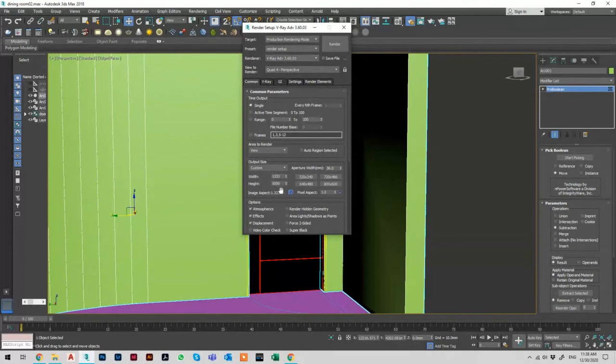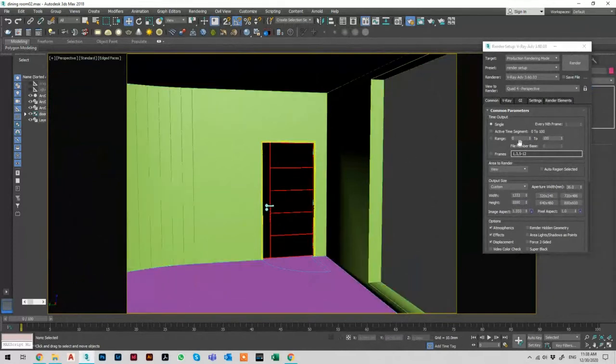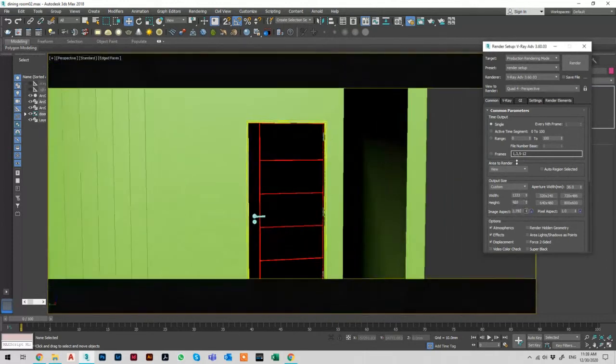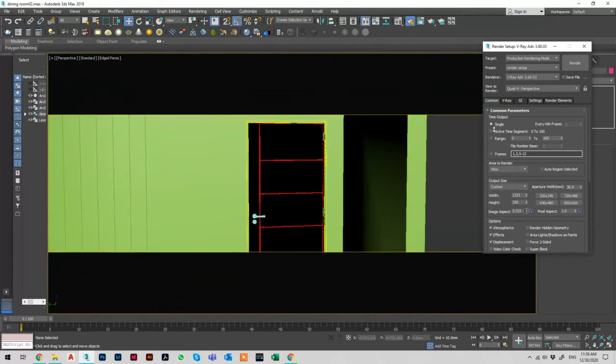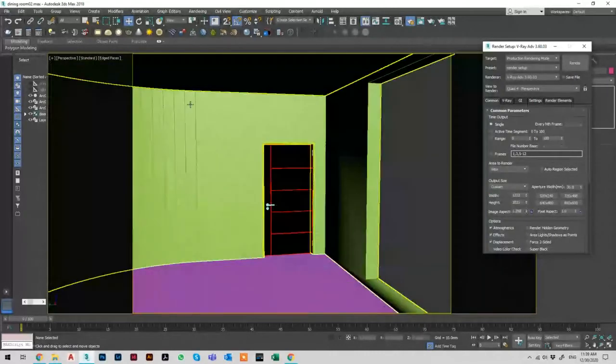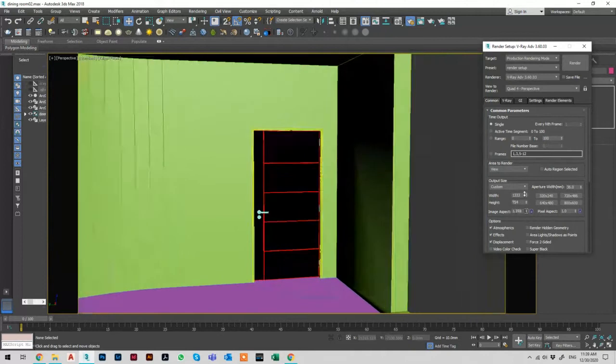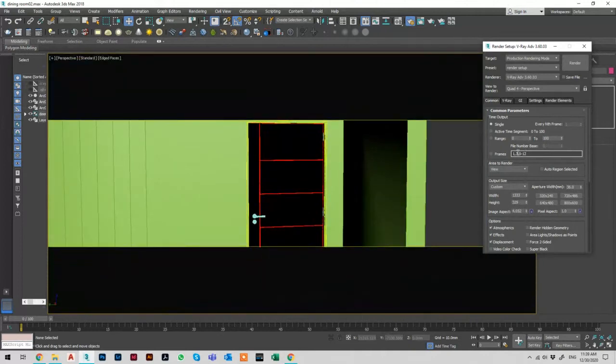Okay. Here you can change the width and height. So you have the image aspect here, which you can see if you click on Shift and F to open the save frame. Okay, so you see this frame here that will show you exactly what you will be rendering. So if I change the image aspect here, which is the ratio between the length and the width, you will see that it will change. So if you're rendering a section, for example, you can increase and decrease the image aspect to fit your section, instead of rendering a full image in 1.4, which is this way, and then your section will be just in this area and all the areas above and below are empty. So you're wasting time rendering something that you don't need. So you can change the image aspect and then you can render the section, for example.